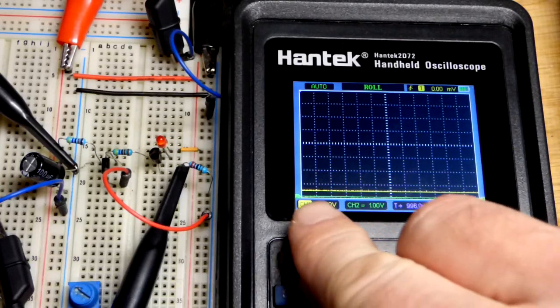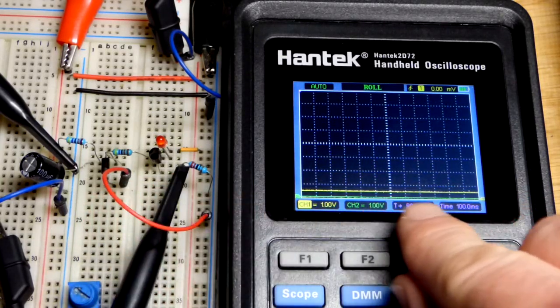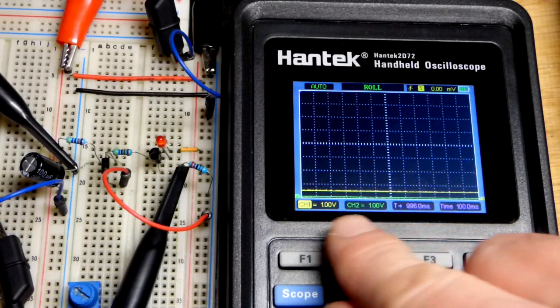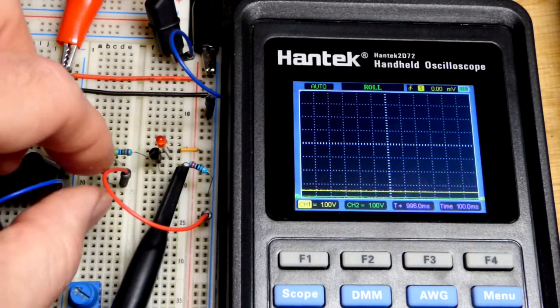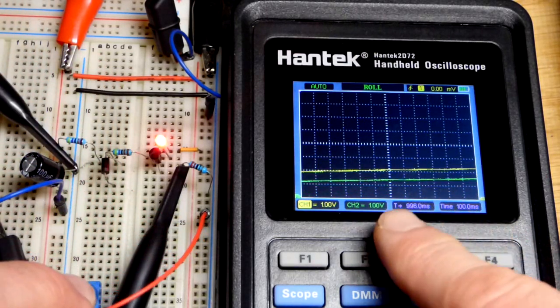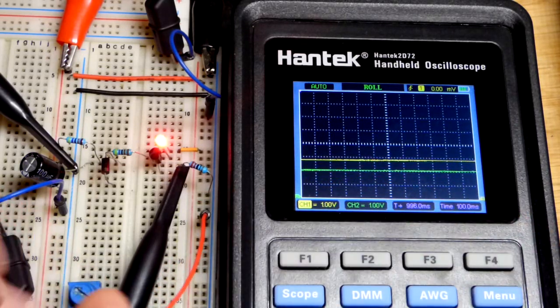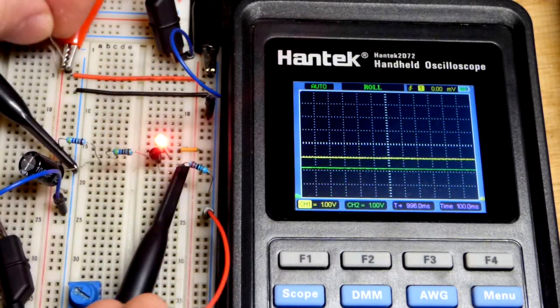And now here you can see the voltages. The yellow line is the voltage across the capacitor being held up at about 0.7 volts, almost enough to turn on the transistor there. And right below it is the voltage across the resistor, pretty much 0 volts. We're going to remove the jumper. You can see the capacitor voltage went up, and then the voltage across the resistor. So as long as the voltage goes up, more current is flowing through the LED, and it's getting brighter ultimately.